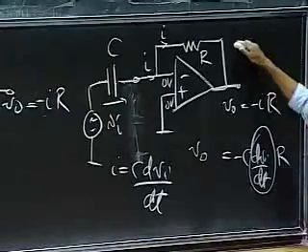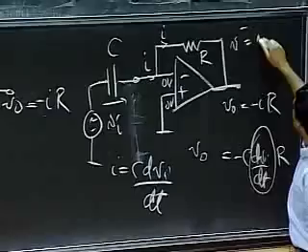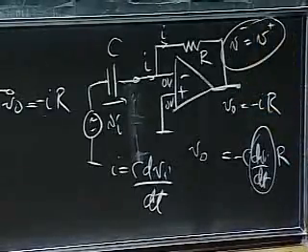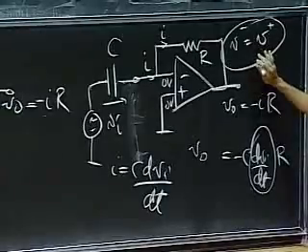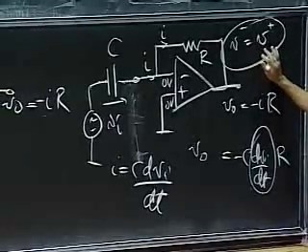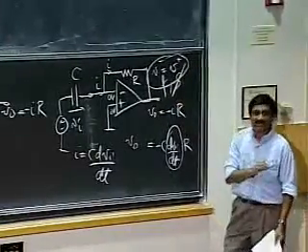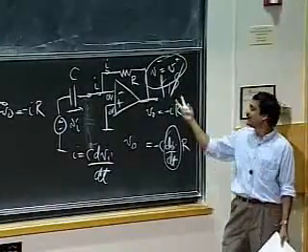So remember this as a closing thought. Remember this V plus more or less equal to V minus trick, and to the extent possible, simply use that trick to analyze op-amp circuits under feedback and not in saturation. Just remember these two.